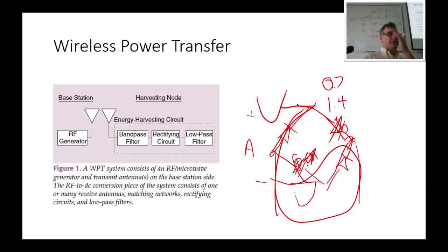In some instances you might be able to do it, but this idea of a bunch of windings, coupled inductors with mutual inductance, the idea of doing this at RF is prohibitively lossy. You just can't make transformers efficiently at RF, especially at microwave and higher. It just doesn't work. It takes up too much space, too lossy.